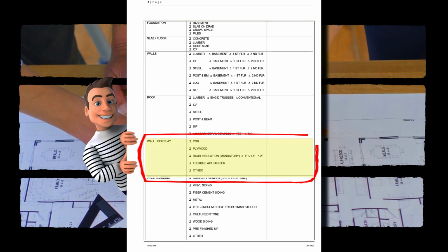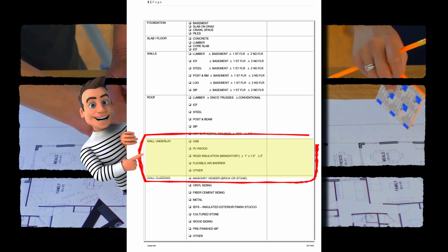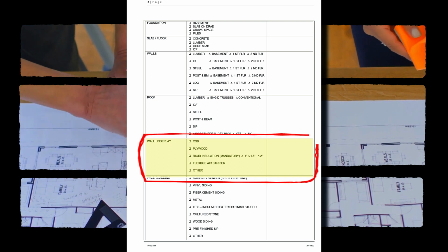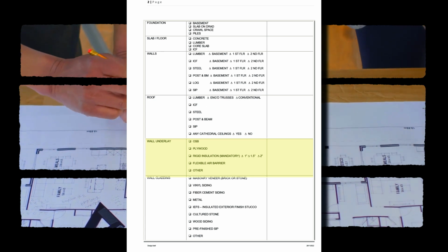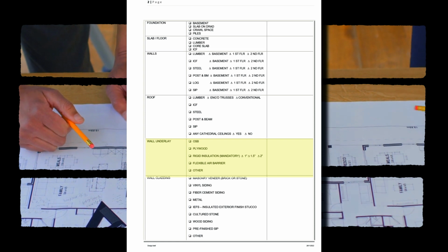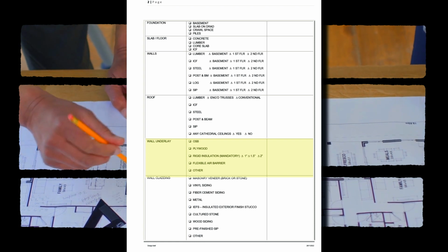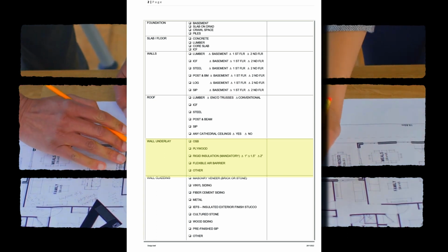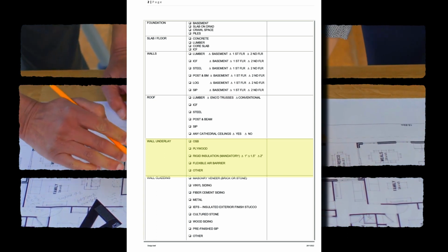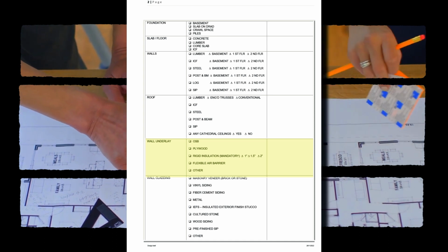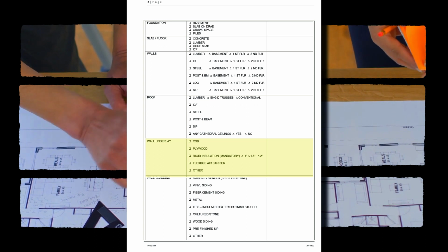The next 4 sections deal with exterior finishes and moisture control materials. The first deals with wall underlayment. You should discuss with your client the type of air barrier system you recommend, based on the type of assemblies discussed in the previous structural section. Options listed are OSB or plywood, which are wood products that must be used in conjunction with other products to be effective. Others include rigid insulation or flexible sheet type underlays.